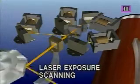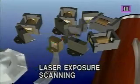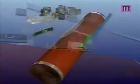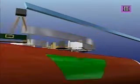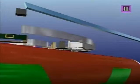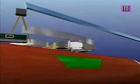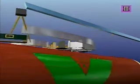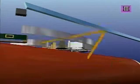In the laser exposure scanning process, the laser diode is turned either on or off, depending on the image signal. At this time, the electrical potential of the drum surface at which the laser beam is directed gets close to 0 volts, and the potential of the drum surface at which the laser beam is not directed remains at -650 volts. As a result, a latent image, which cannot be seen directly by the human eye, is formed on the drum surface.